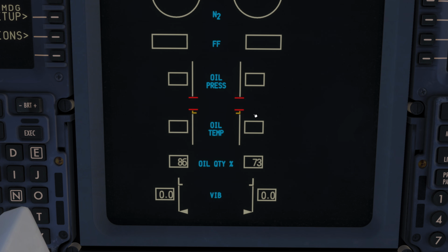Now those are the two meanings for the oil pressure as well as the oil temperature. Generally speaking, again, normal values will be recognized by your electronic engine controls, and if they go abnormal, then it's a good idea to have in mind what that may indicate. But from a pilot's perspective, if they go out of the ordinary, you generally just have one course of action: shut the engine down before it destroys itself.